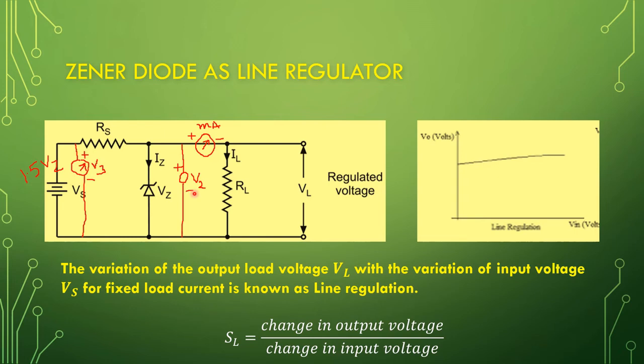Now increase the input voltage in small steps and at each step note down the Vs voltage.